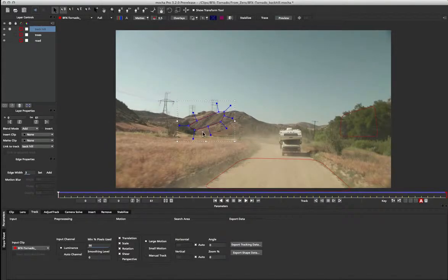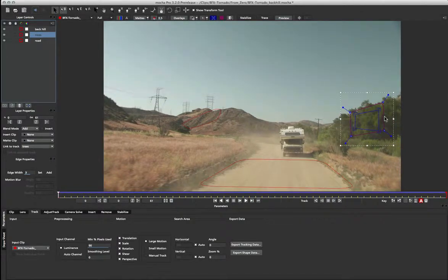Now the first thing I'm going to do is turn on my surfaces again and just make sure that my surfaces are small enough. Now you can see here my surface at the moment, it's kind of peeking outside the shape, and we want to, when we're doing a camera solve, make sure it's inside our shape and actually reasonably small. We want to keep surfaces small because the camera solver needs to work out the projection of these nulls, and the smaller the surface, the more accurate the nulls are going to be. So if we look at this one's actually not too bad, and over here we can probably keep this one about this size.